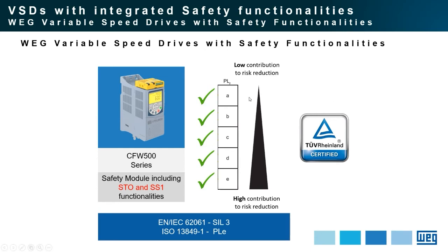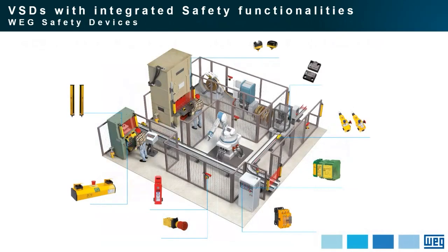So it is possible to use the CFW500 with this safety module, this yellow module installed here on the top of the drive, in applications with low contribution to risk reduction, up to the higher contribution to risk reduction. Remembering that all of them, CFW700, CFW11, and also the CFW500, are according to the TÜV recommendations and are TÜV certified.